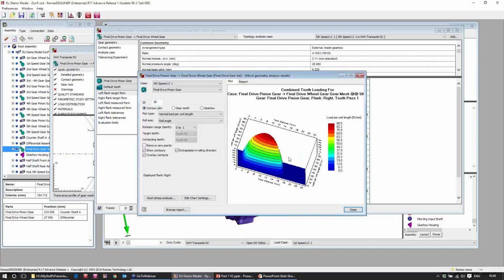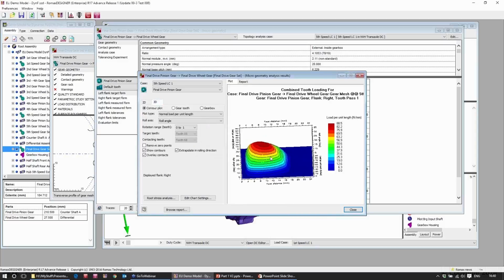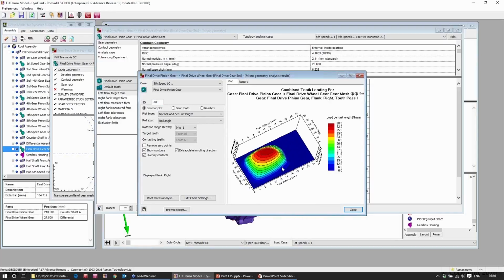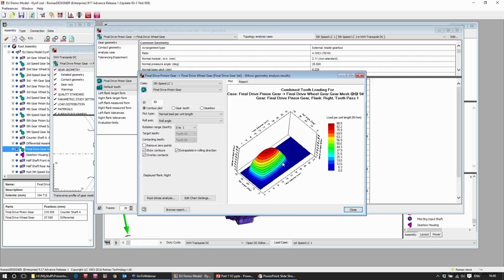The contact behavior of this gear, we've got contact here. It's away from the edge of the tooth, which is a reasonable contact. It's in a pretty small area. That's because we've got quite a lot of crowning on this. In this particular example, we could probably do a better job of that by optimizing that, and we have the capability to do that. But this is part of the way of checking how, as well as looking at the noise, how this affects the durability.